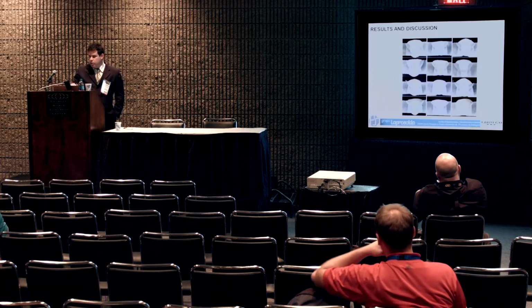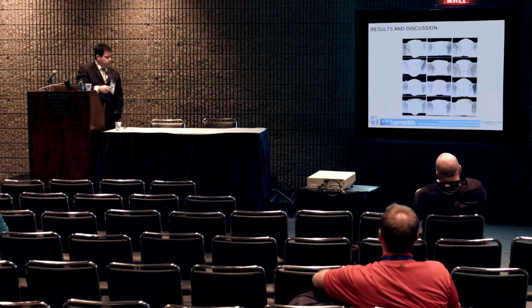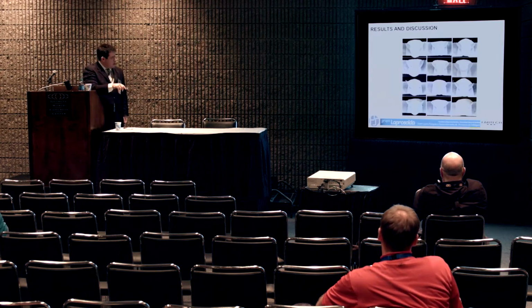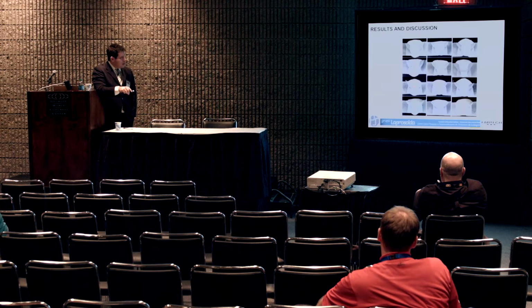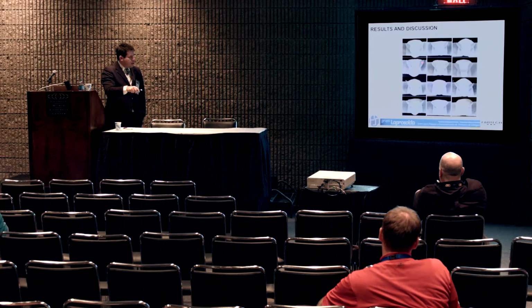Here are some macros. You may notice that CMT and RMD are free from defects. Here, with STT, you have some lack of fusion, but those were a previous set of macros. We redid the tests and increased the current a little bit, and we had no more lack of fusion for STT. It was perfect.